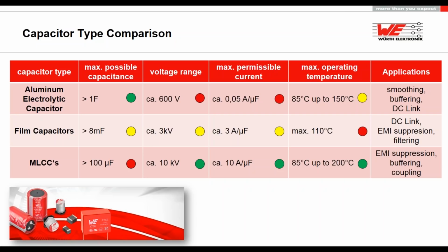Nowadays, more and more promoted, you find MLCCs as a replacement for E-caps or tantalum capacitors, because they are now in the microfarad range. And it's interesting to replace a few E-caps or tantalum caps, but you really have to take care of some specific things and dependencies, which I want to talk about today.